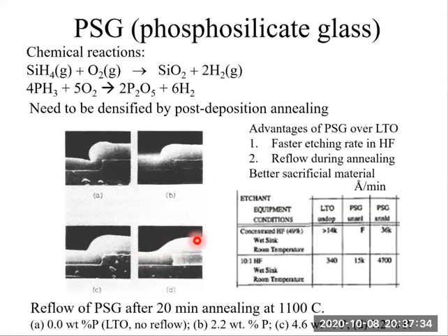And this helps to planarize the surface. So it is desirable for many applications. So in many applications, we prefer PSG over LTO. For LTO, no reflow.